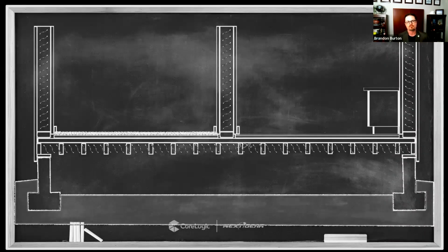What is the role and purpose of air movement? So in terms of a drying environment, obviously what we're trying to do is remove excess moisture from the environment, not only to bring the building materials back to a normal moisture level, but we're trying to do that for a purpose, right? And that purpose is to prevent the damages that that excess moisture can cause, not only to what is wet, but the surrounding materials that can become secondarily affected.